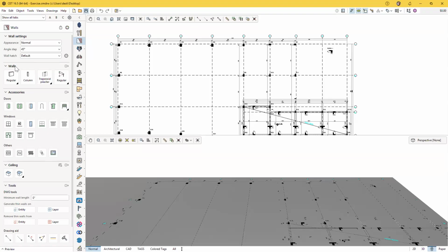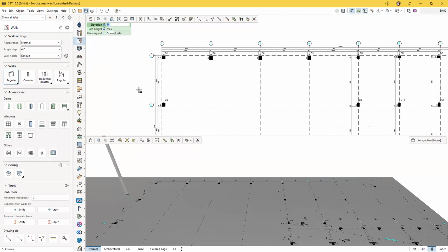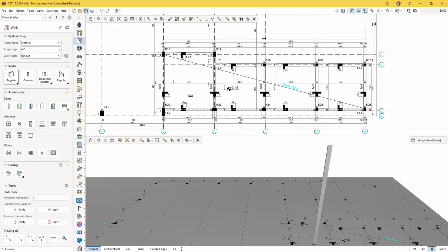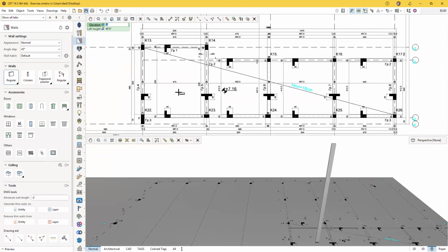So we're going to come straight down to where it says walls. Now you'll notice that the first tool is a nested tool group. So we have thin, regular, and thick walls, and then we also have a continuous wall tool. Today, we're going to be looking at the regular wall tool. So this one's going to take care of pretty much all of your needs. Your walls are going to be able to be stretched. They will have stretch nodes on them after they are placed in your drawing. So you can feel free to use these however you need to. And if you make any kind of changes, or if you need to make any adjustments, you can absolutely change them using those stretch nodes.